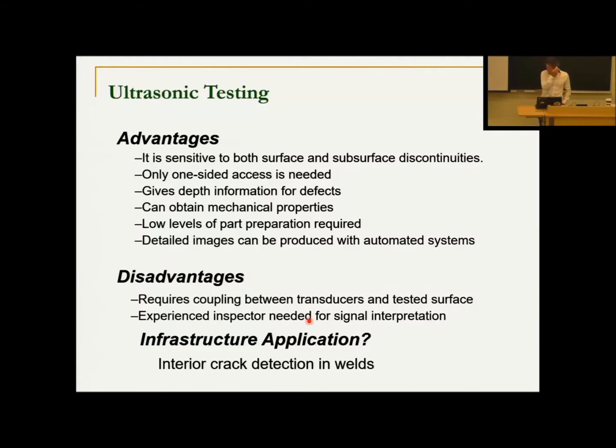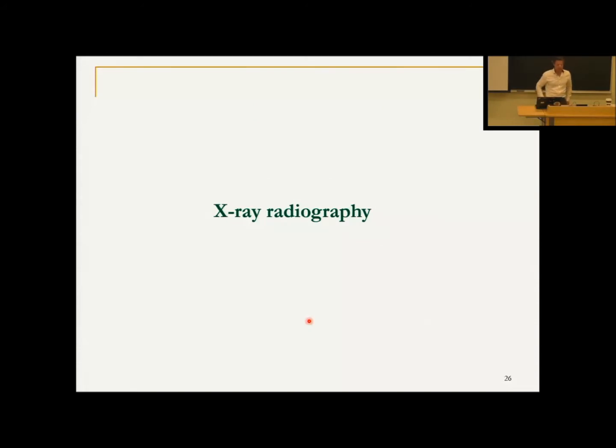But this has lots of application, and perhaps the most common application of ultrasound is finding, inspecting welded connections, looking for cracks and voiding. It's very good in a practical way in the field. Now, the next method that I'll talk about, X-ray radiography, penetrating radiation, also can be applied for the same job, looking through welded connections, trying to determine if they are cracked or have some other sort of problem. But the phenomenon is totally different.